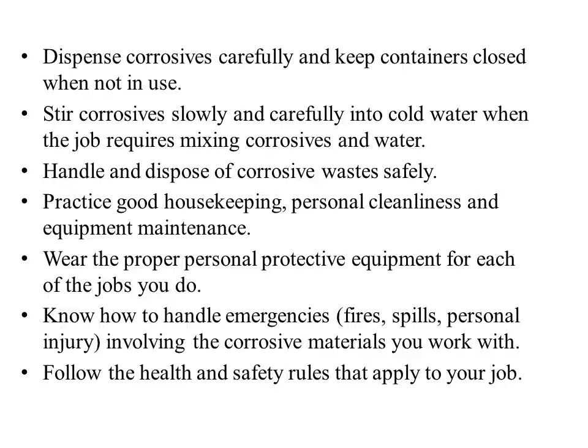So next point, stir corrosives slowly and carefully in cold water when the job requires mixing corrosives and water. Sometimes corrosives have to be mixed with water, and this mixing is usually done with cold water. When mixing water with corrosive, the water is slowly poured and then mixing is done. If the water is poured fully or suddenly, there is a chance the chemicals will start boiling, resulting in vapors, fumes, or even spillage. So this has to be avoided.